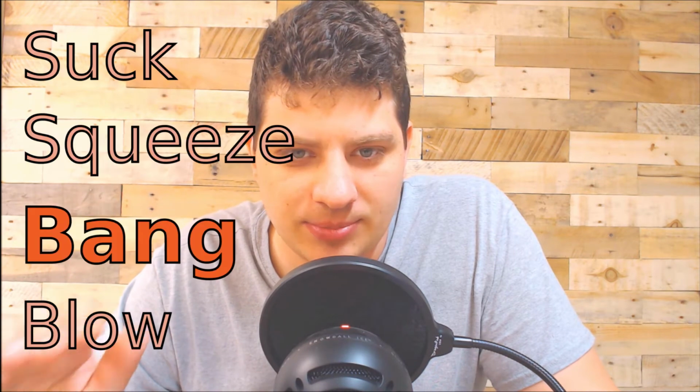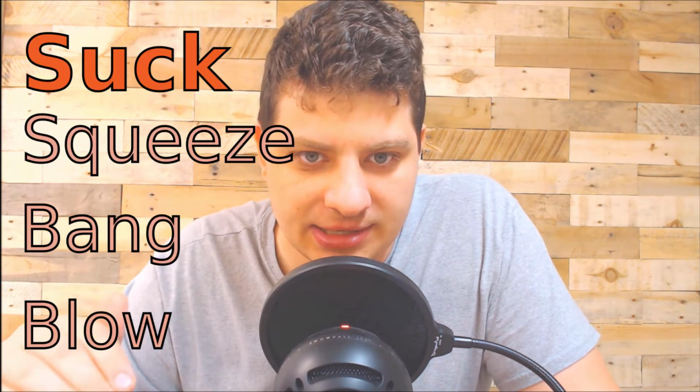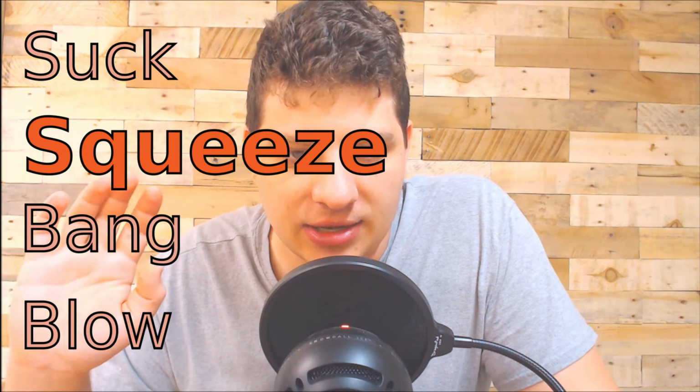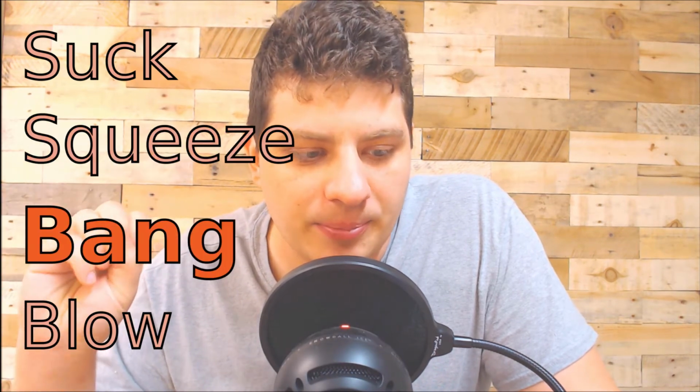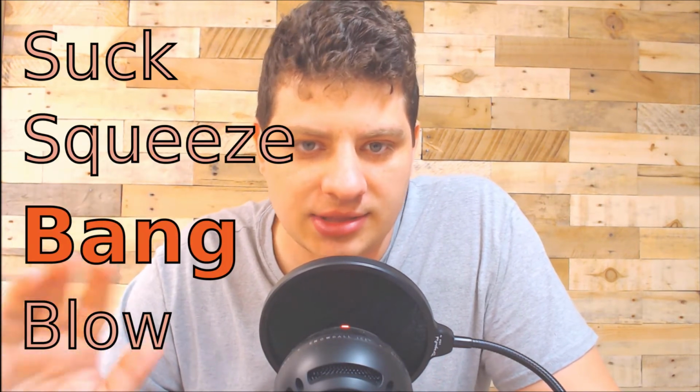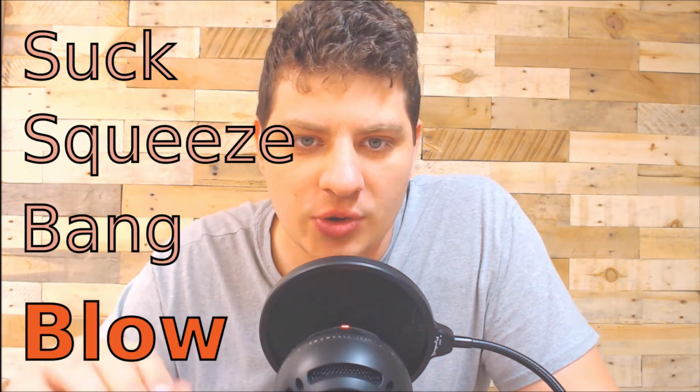A Brayton cycle engine, a jet engine, follows all of the same steps as a normal combustion engine: suck, squeeze, bang, blow. But a Brayton cycle engine has an advantage where it's doing all of these things continuously at the same time. If you go to a piston engine, and let's just look at one piston, it goes through 4 steps. It sucks, it brings in the air; squeezes, it compresses the air; bang, it ignites the air fuel mixture; and then blow, it exhausts.